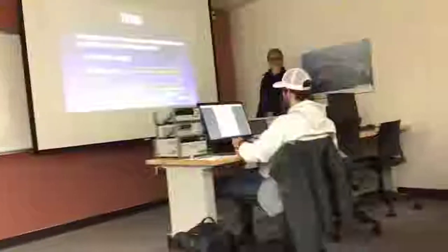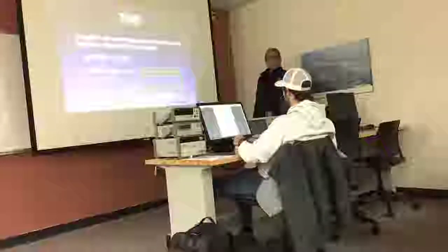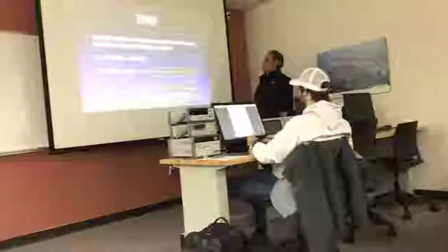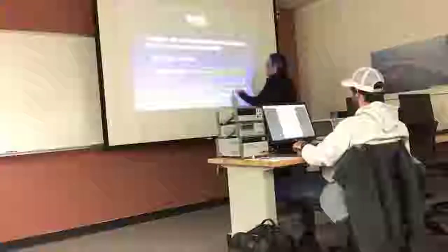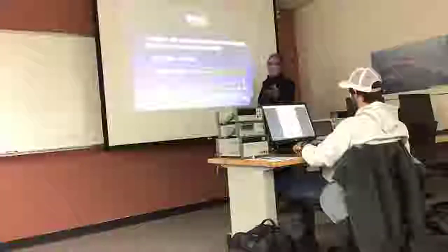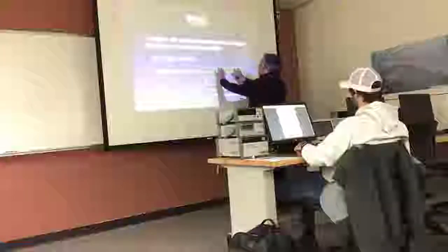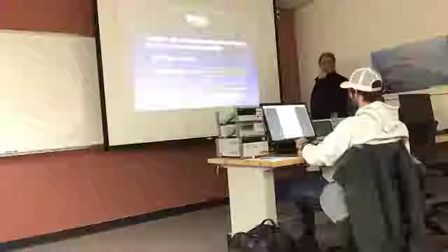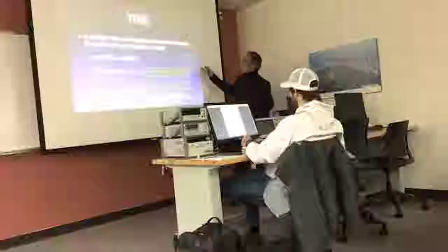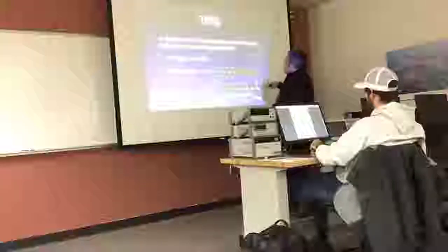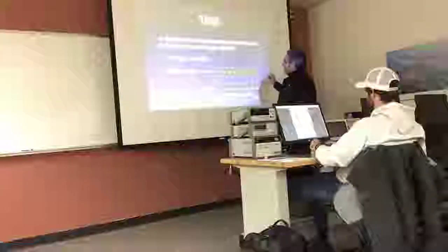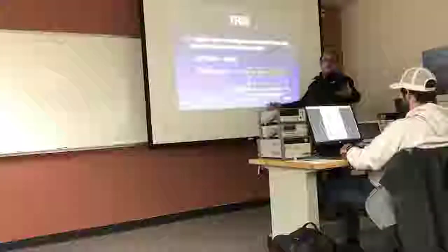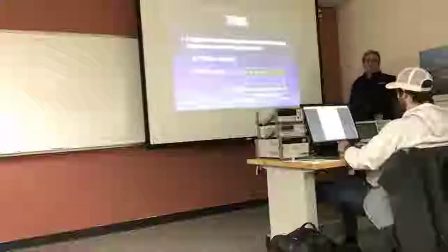Also, you don't have to set it all at once. Correct. You could set it, or if you want to, let's say I just want to change the behavior of only that pin, you could use bit masking to avoid changing the behavior of anybody else but the pin that I want. In this case, because I just want to make sure that I get everybody a startup value, kind of like in your setup, I want to get started somehow. Then I set it up this way.